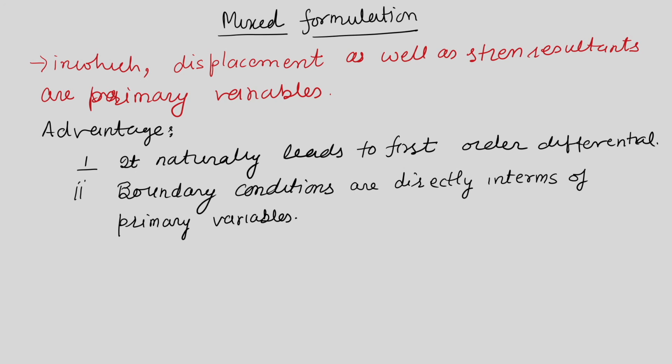In the previous case, for displacement, we had to define a new variable so that we could convert the second order differential equation into a first order differential equation. But if we choose the mixed formulation approach, it naturally converts to a first order differential equation. The next advantage is that boundary conditions are directly satisfied in terms of the primary variables. For example, if the boundary condition is clamped, then the displacement based approach gives no problem: u1 is 0, u2 is 0, w is 0, psi 1 is 0 and psi 2 is 0.